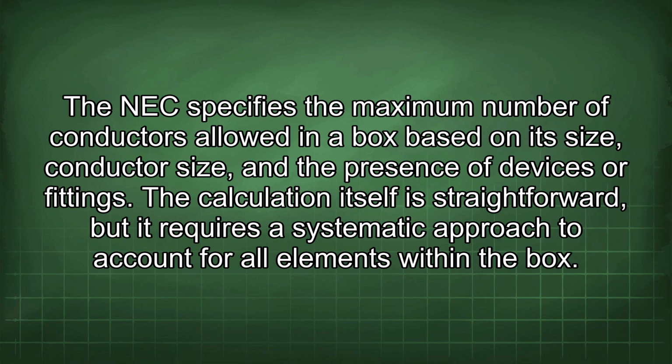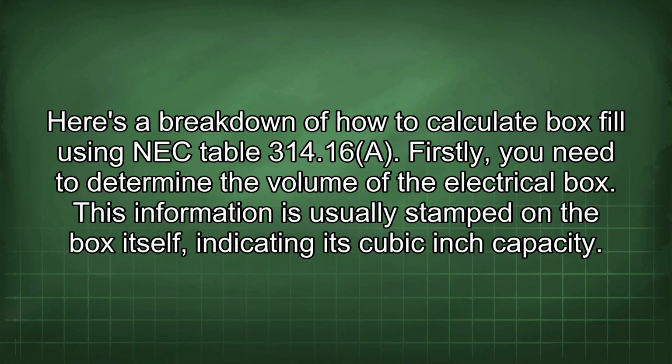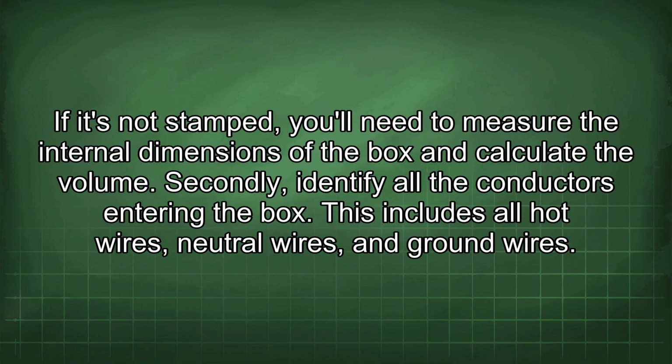The calculation itself is straightforward, but it requires a systematic approach to account for all elements within the box. Here's a breakdown of how to calculate box fill using NEC Table 314.16(A). Firstly, you need to determine the volume of the electrical box. This information is usually stamped on the box itself, indicating its cubic inch capacity. If it's not stamped, you'll need to measure the internal dimensions of the box and calculate the volume.